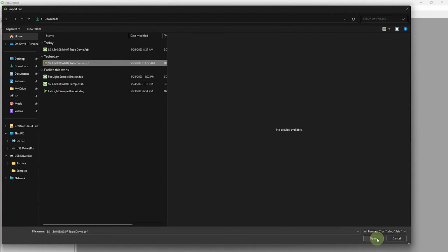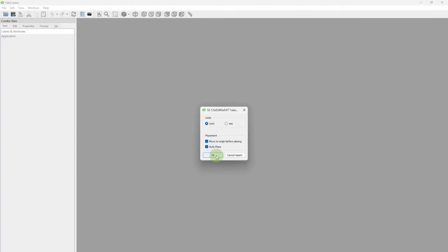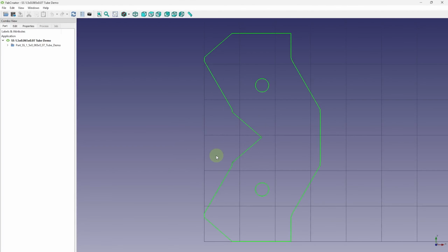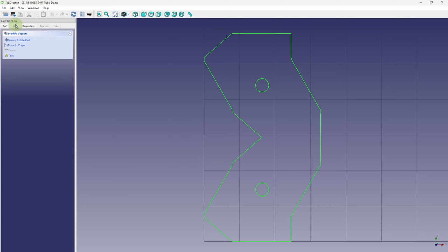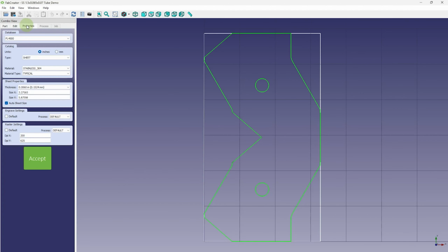We import our drawings, and if we've layered it into drafting software, it will automatically import that geometry into those process folders. You can change the order or process for each geometry the same way as before, and island detection and path optimization works the same. The Edit tab has all the same functionality of the sheet parts we processed for your tube parts.